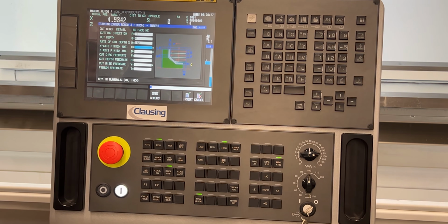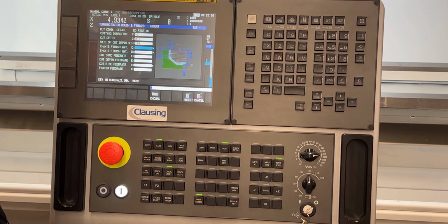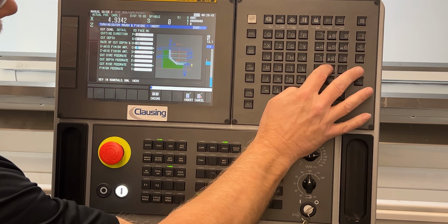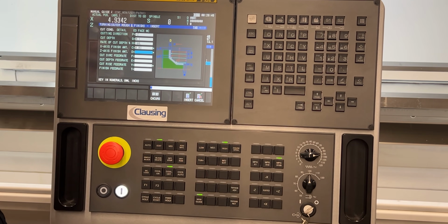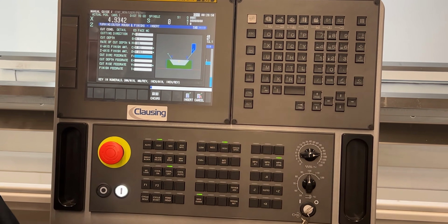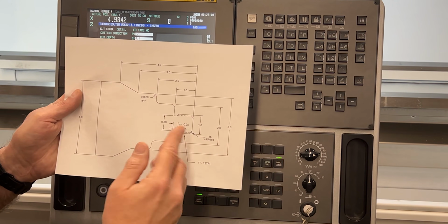The next thing is my X-axis finish amount. What do I want to leave for finish? Being it has asterisks over here, that means you don't have to fill it in, but I want to leave material for the finish pass. So I'm going to put in there, let's say 30 thousandths for the X, and then for Z, I'm going to leave, let's say, about 3 thousandths. The reason I'm leaving so little is because I only have 3-degree relief on my tool, and I don't want to bury the tool when I come into a shoulder.